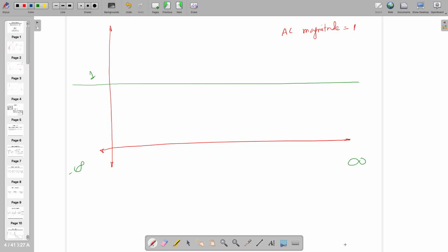So white noise, we know that white spectrum has every color in it, right? So white noise is the one which has noise available at every frequency, and color noise is the one which is available at a particular frequency. So generally we say that this particular circuit is having colored noise at, let's say, 1 megahertz or sometimes 1 kilohertz, meaning at that particular frequency I am seeing the noise or some unwanted signal.